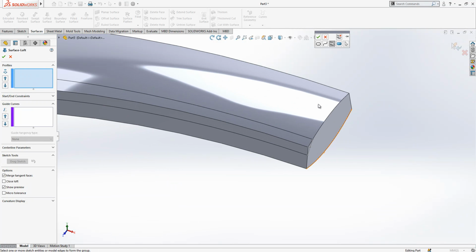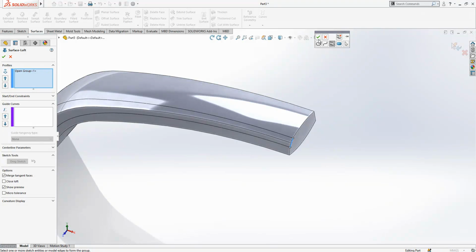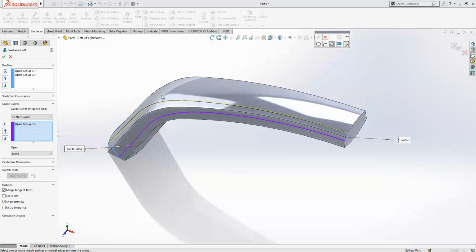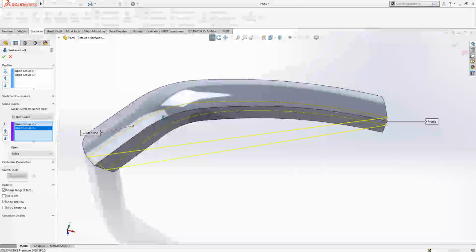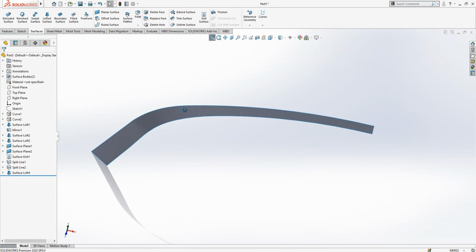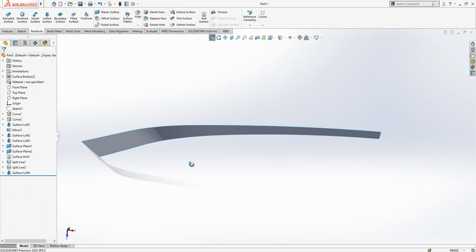This is a real model as I mentioned, only the dimensions a bit different because I don't want to be disrespectful to my customer. And I will not complete everything as well. So this is to object, guide curve 1, selection manager, and guide curve 2. Everything fully constrained, and let's say, okay, what do we get now? We get a surface as you see on the screen.